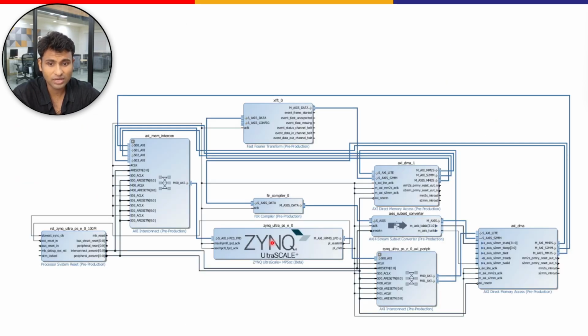Next thing which we look at is the AXI interconnect. This block manages the AXI bus interconnection between multiple masters and slave interfaces. It also acts as a communication hub directing traffic among the connected IP blocks. It handles several AXI ports which you can see mentioned here, and it facilitates high bandwidth data movement between the processing elements, the memory controllers, and the different IPs which are connected to it.